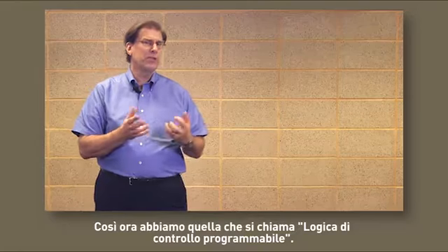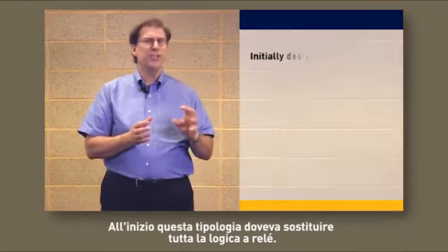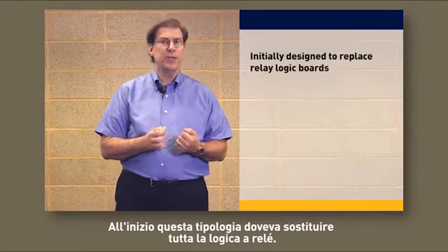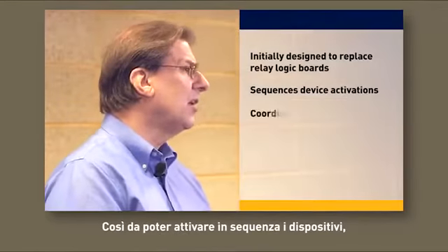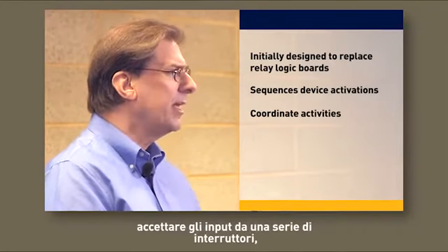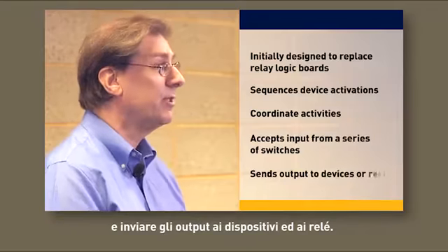So they came up with what they called programmable logic controllers. It was initially designed to replace all that relay logic. So you wanted to be able to sequence device activations, coordinate activities, accept inputs from a series of switches, and send outputs to devices or relays.